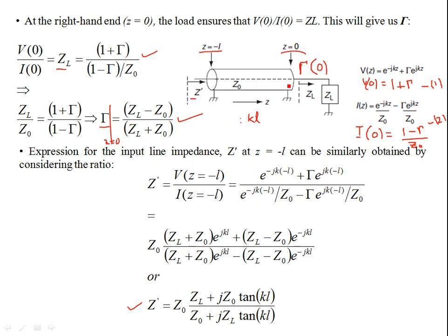Okay, call it EL, whatever you want to say. So this is the electrical length of the line, and this is the phase difference that the line imparts. So based on this small l or KL electrical length, you have the impedance transformation, okay, and that's in terms of Z naught and ZL. And we discussed how short circuit, open circuit conditions, and arbitrary inductive or capacitive load conditions change the impedance down the line as a function of small length L or the electrical length.